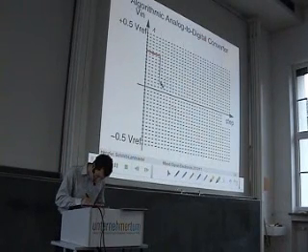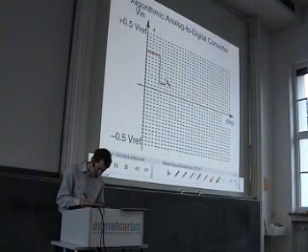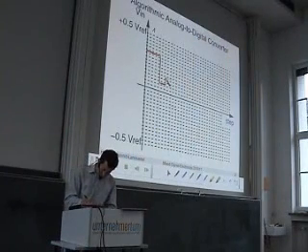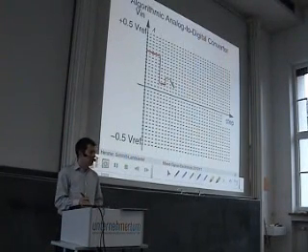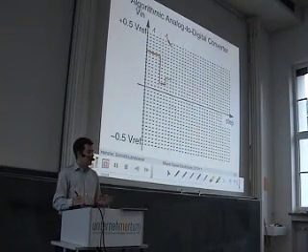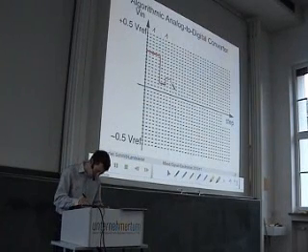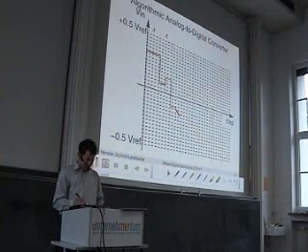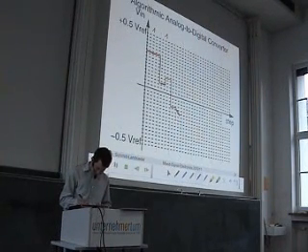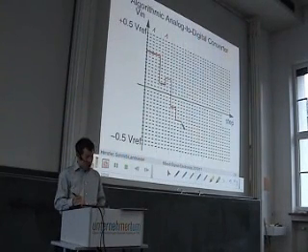So we go down here, we decrement it by Vref over 4, and this is our remainder, and we double this error voltage and end up here. This is still larger than 0, so we set the respective bit to 1, but now we again decrement it by Vref over 4, and we go down here and end up here. So this is our new error voltage, and we double this new error voltage and end up here.